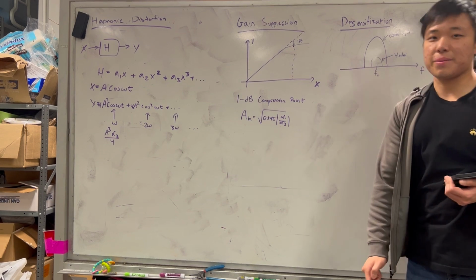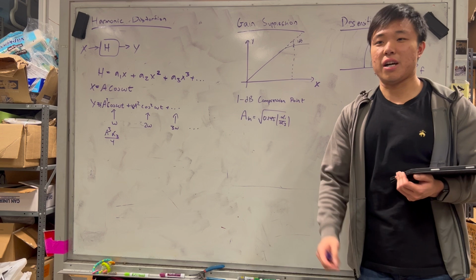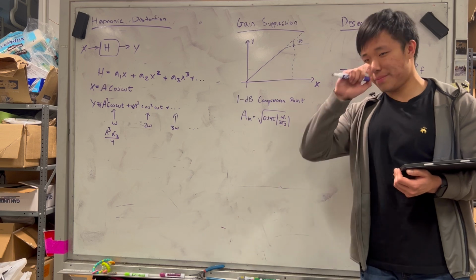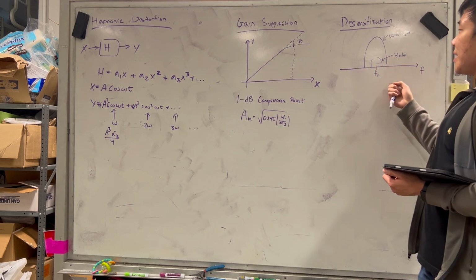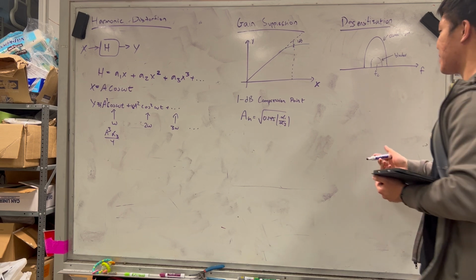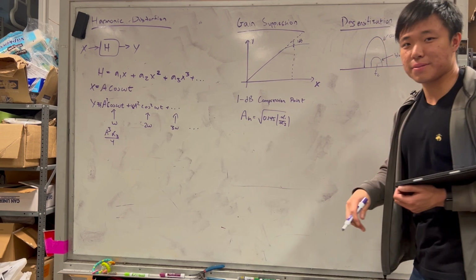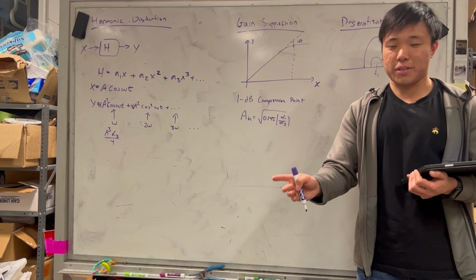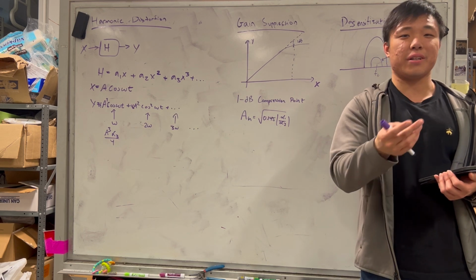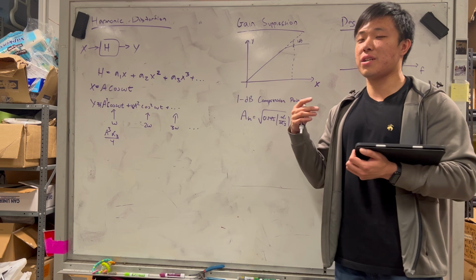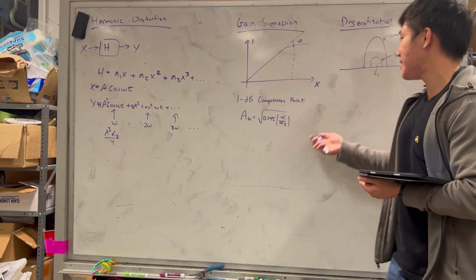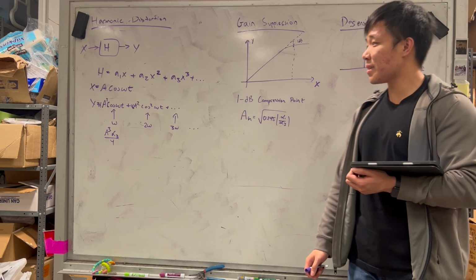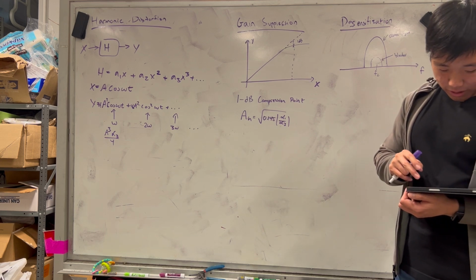Whenever you send something, let's say I'm trying to communicate wirelessly to someone else, other people can also use that channel, right? So that could cause this, but a main cause wouldn't really be that. We would really see this more in a duplexer system, where you have a duplexer that switches between I want to transmit versus I want to receive. Typically, the power that you're transmitting is going to be significantly larger than whatever you're trying to receive. And if you put them too close to each other, then you have this issue, because you're transmitting and receiving at frequencies that are comparable to each other. That's called desensitization.